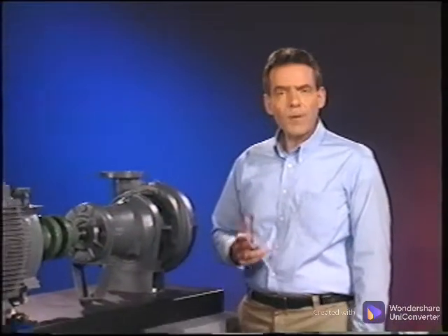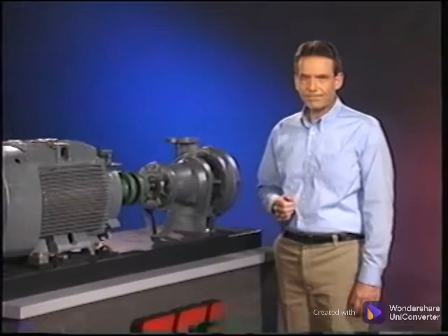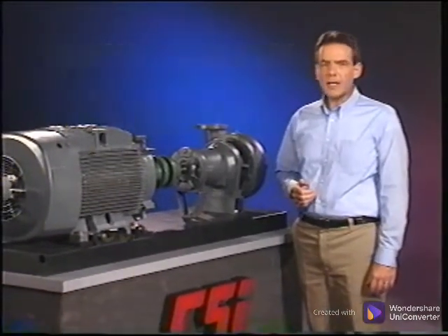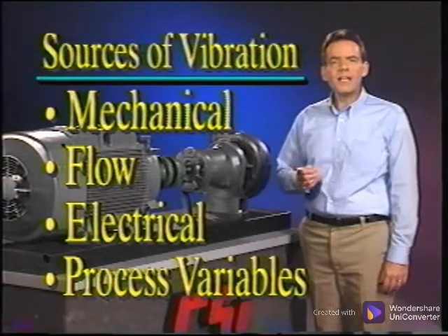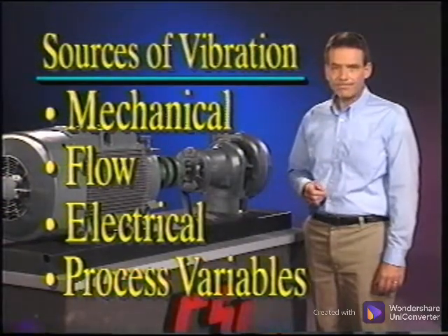Here we can see how each of these peaks were generated because of specific mechanical properties. It is important to understand that there is a mechanical or electrical occurrence represented by every peak in the spectrum. The source of the mechanical vibration could be flow, electrical, or some other force, but the effect we measure is mechanical vibration.